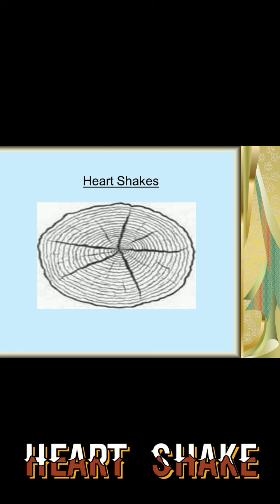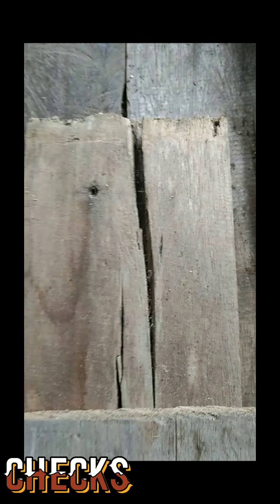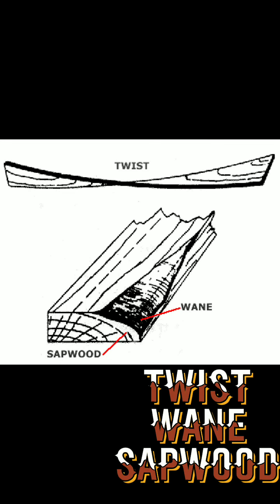usually along the heart. Compare ring shake. Checks are small separations of wood fibers in the longitudinal direction, not penetrating as far as the opposite or adjoining side of a piece of sawn timber. They usually result from seasoning, developing during seasoning, and are distinct from heart shakes.